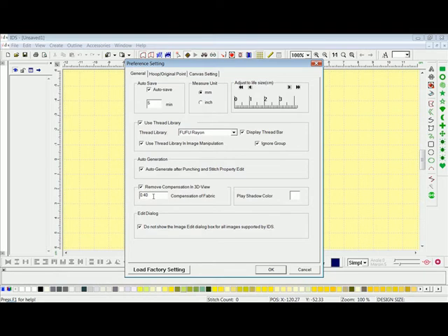Now, pull compensation, that is the stitches that extends beyond the actual line of programming, meaning that if you have a square, your stitches will extend beyond the square to accommodate for push and pull of the fabric as well as for the sinking of the stitches. When you view the design in the 3D view, it will take away that compensation of fabric to give you more of a rendered look. This will not change your stitch settings, but will just change the look on the screen.